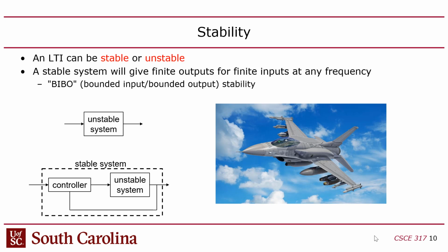You can model that by just multiplying the two transfer functions together in the S domain. Now that's the open loop control. The closed loop control requires a little bit more tweaking, but basically by representing things as these LTI transfer functions, it makes it easy to take pieces, including plants and controllers, and connect them together like Legos. Just take blocks and create this block diagram.